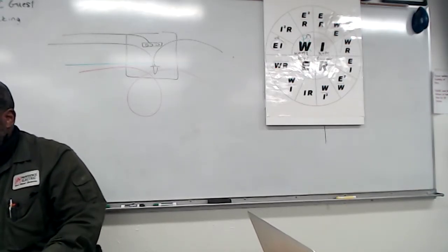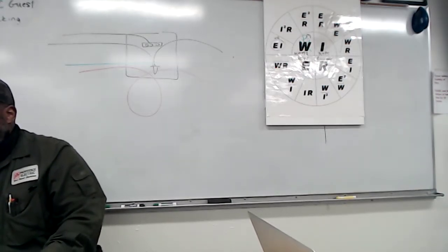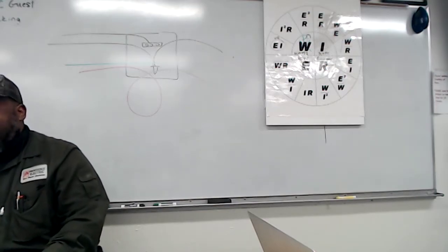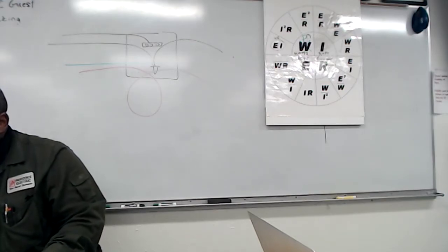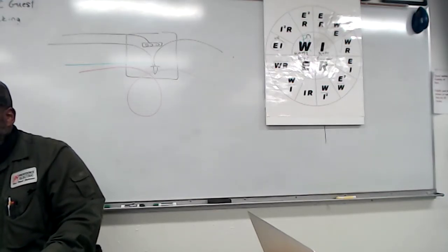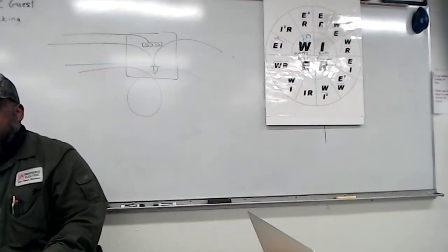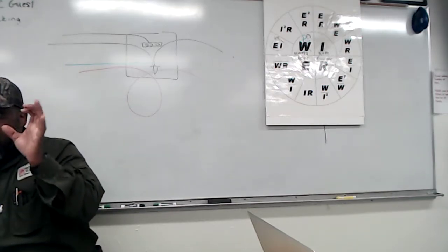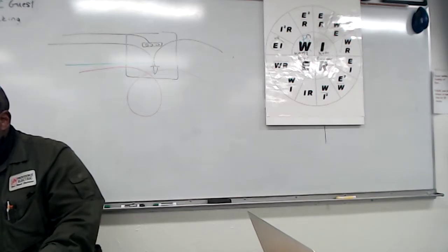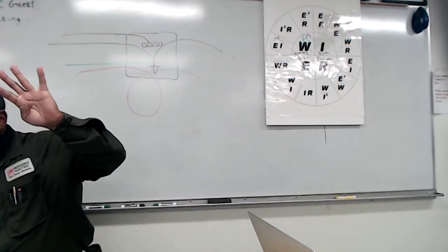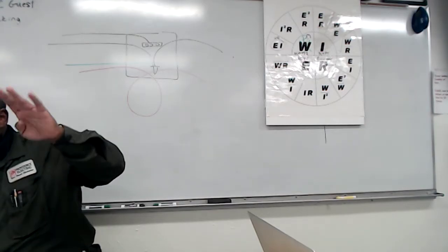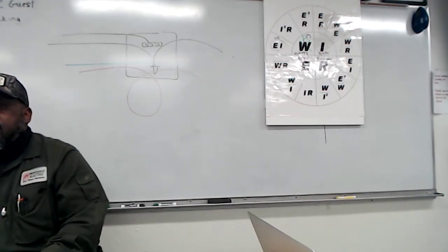That's very important. If you have a yoke that's bigger than 2 inches, then it gets counted double. So if you got a dryer plug, oven plug, with them big old plugs, it gets a double allowance. You count it 4 times, right? It gets 4 allowances.